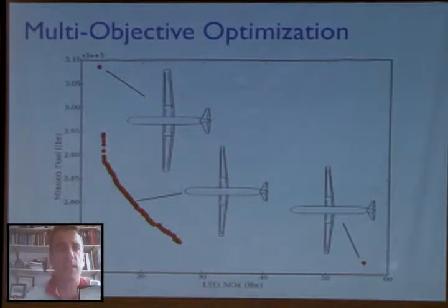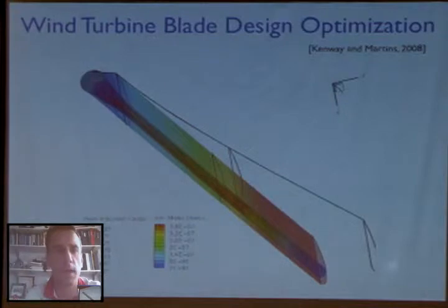On the last slide here, what I'd like to show you is another application that's not aircraft related, but because it involves aerodynamics and structures, we were able to do that in our research group. And it's an application to wind turbine blade design optimization. This is the case I like because the starting point that you see there, the baseline design, is really not being designed at all. This is basically a plank and would not work as a wind turbine blade. It has no twist, it has no taper, the structure is constant thickness, so it's very inefficient.